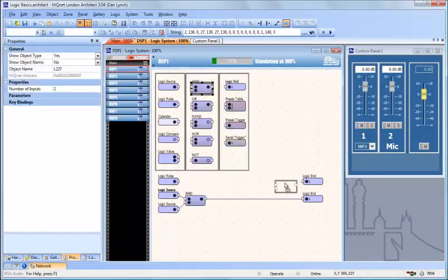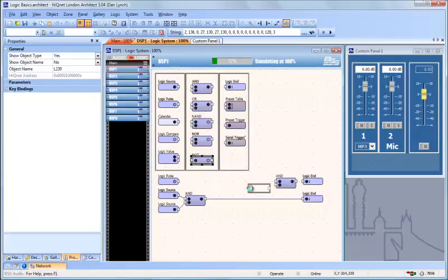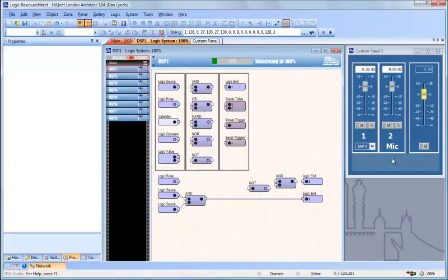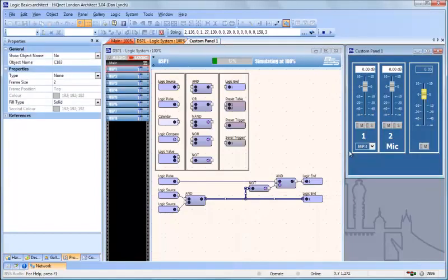Let's grab another and a not. When do we want this light on the control panel to flash? We want it to flash when the logic pulse turns on and not the master mute. In other words, we want an on-air indicator. If everything is muted, no flashing light. Unmute it, we have an on-air indicator.